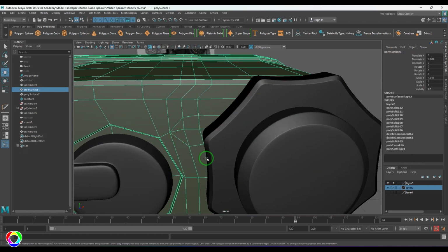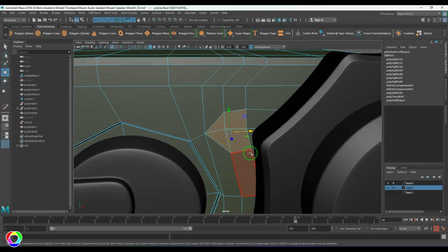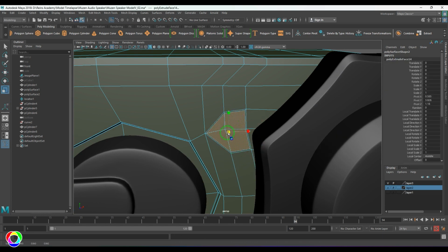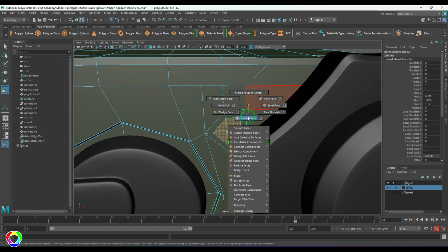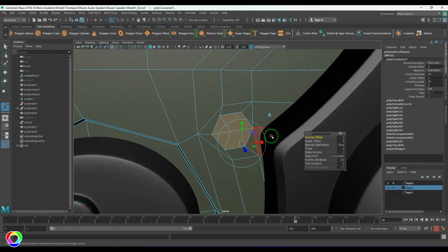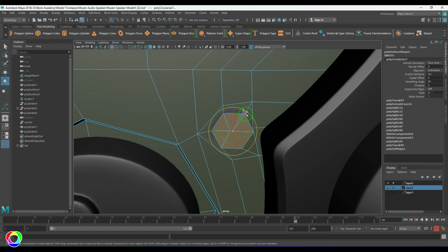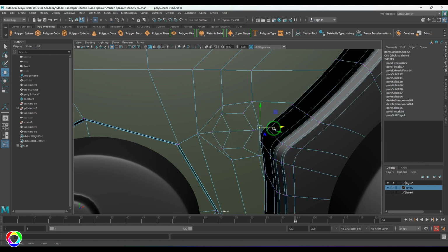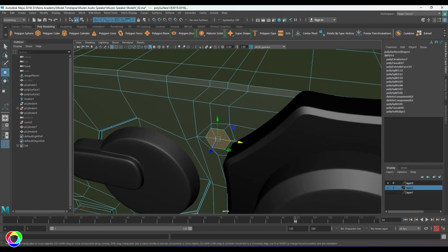And those lines are a must, important for me. I'm selecting those faces, extruding them, and applying a circularize tool just to relax this vertex, and then select those faces.